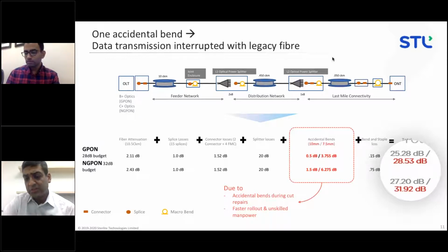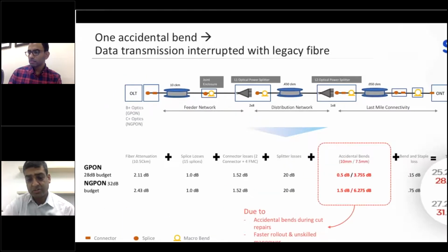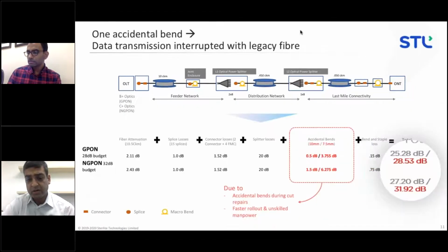Now, the reason why this happens is that G.652D is very, very susceptible to macrobend loss. The construction of the fiber does not include the trenches that are typically present that limit your attenuation losses due to macrobends. And as a result, you very, very quickly put the network outside of this power budget, and you have a failed network.